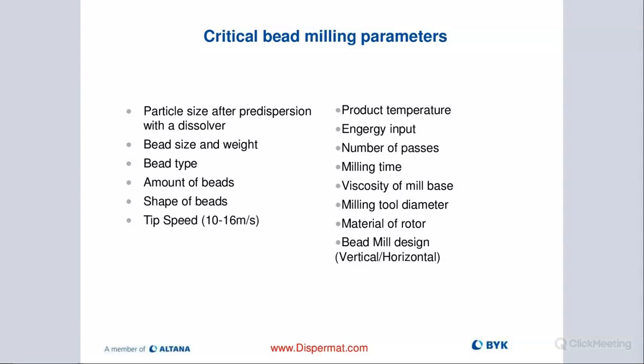Bead volume, of course, depends on the type of mill we are using. Using a basket mill, a vertical bead mill, which has a much higher bead loading, or a horizontal media mill, each mill has its own specifications. So there is not one set rule that you always need to use a certain amount of beads. It depends on the milling chamber size and, of course, the type of mill that you're using. So that would be in the operator's manual. You can usually see a table that details exactly the fill rate of the milling chamber with beads.